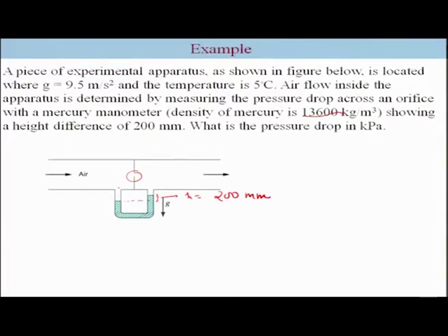So in other words, what is the pressure drop, let us say from here to here, and the pressure drop from 1 to 2 can be written as simply here. Why? Because of course the density of the air is extremely small and this height difference will not bother. The density of the air is close to 1.2 kg per meter cube. Now we have done this exercise before, that the pressure P1 minus P2 is nothing but (rho 2 minus rho 1) GH.